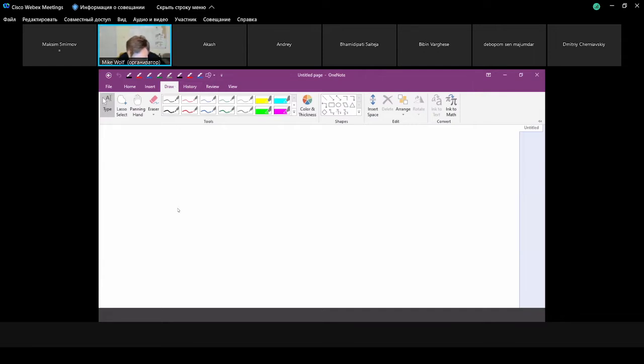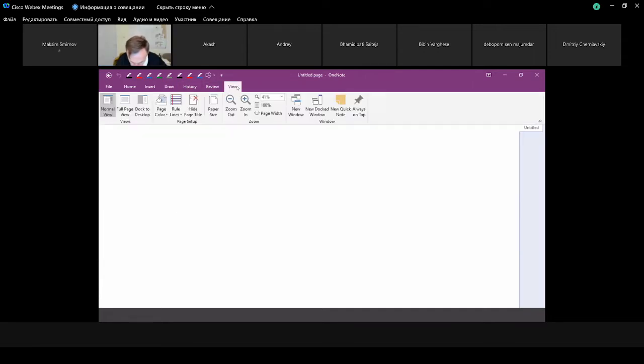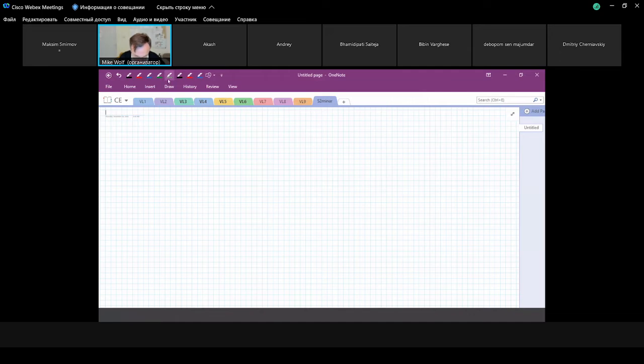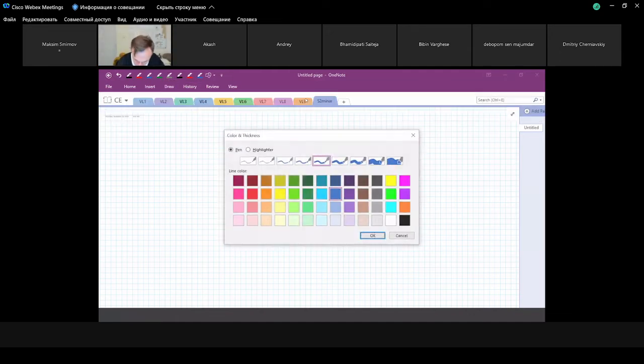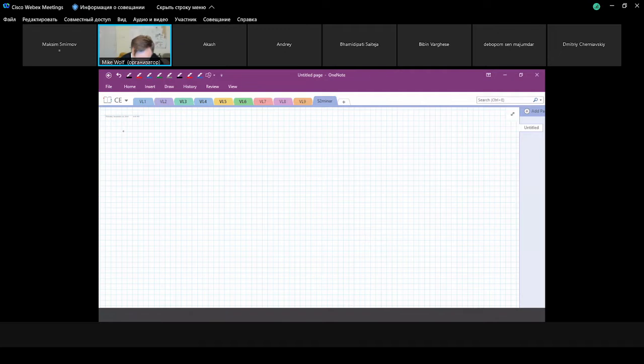So now I start with task number 5.1. You can take a look at the internet and you find the tasks. And then you see, okay, consider the following 4 energy signals. Now we have 4 signals and we want to obtain a geometric representation of these signals, so a linear combination of the basis functions. We need to find the basis functions and the signal vectors. And then we can also find the minimum Euclidean distance, for instance. But this is not asked in this task.